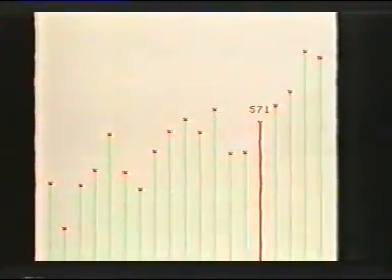So the accuracy of the representation of the analog input would be very dependent upon the size of those time slices. You can actually see it on that original graph. When I was moving it very slowly, it gets a fair representation of the movement. When I moved it very quickly, obviously I was moving it further in the time slice that was allowed. That's the major problem with analog devices. You must sample very frequently if you're to get an accurate representation. So 2 analog inputs there we've dealt with.